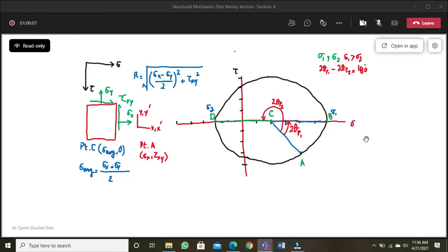So this was about principal stresses and the principal planes. You can see the Mohr circle is so simple. I have got my principal stresses, and I have also got the orientation of the principal planes. Now I have to calculate the shear planes. So how will we calculate the shear planes? We have said that the maximum shear will be here.